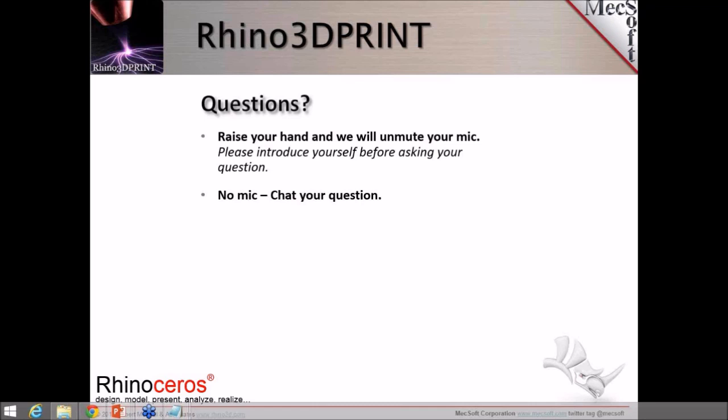And then we've also added tools that are very specific to the 3D printer. For instance, AutoFix, mesh smoothing, mesh refaceting, creating slices for debugging purposes, and then the alignment and fit of the mesh geometry to the printer volume, ability to load multiple printers, checking for mesh overhangs, and checking for the printer volume fitting criteria. Things of that nature we've added, which are completely different from the Rhino tools and really are application specific. And also, we are working on more tools. You will see them come out in the future that are very specific to 3D printing. So short answer, yes, there is overlap, but we do have a lot more application-specific tools in Rhino 3D Print.